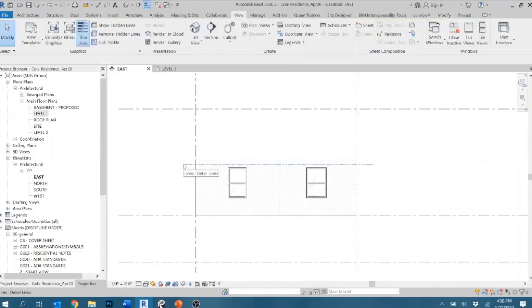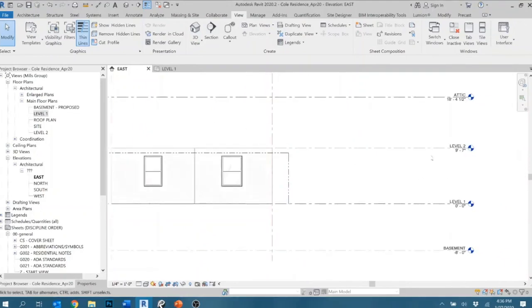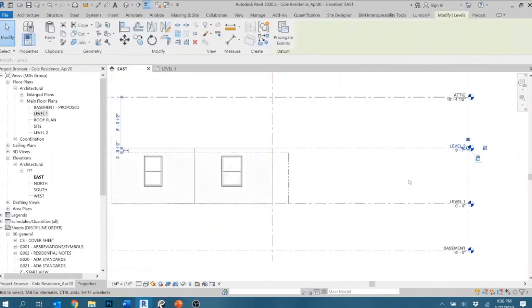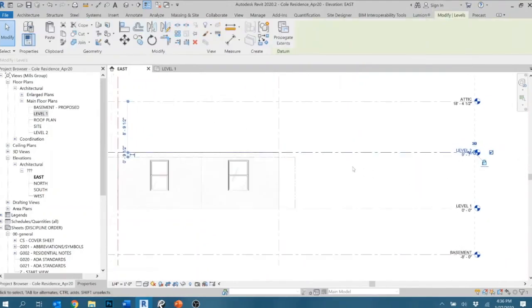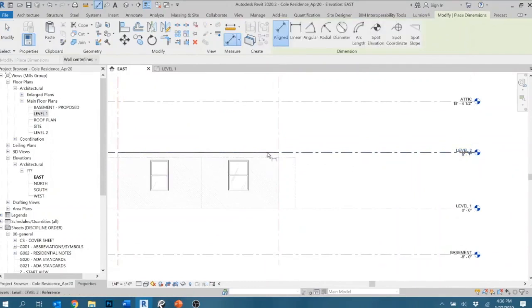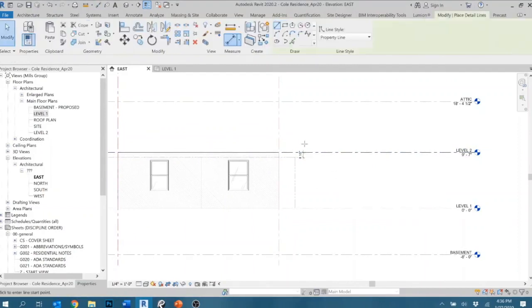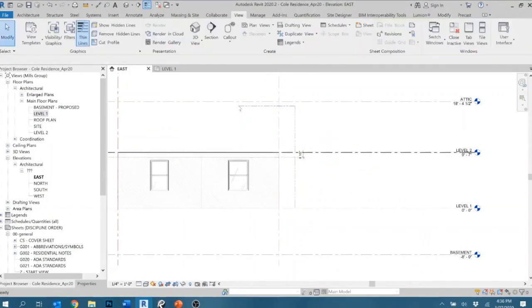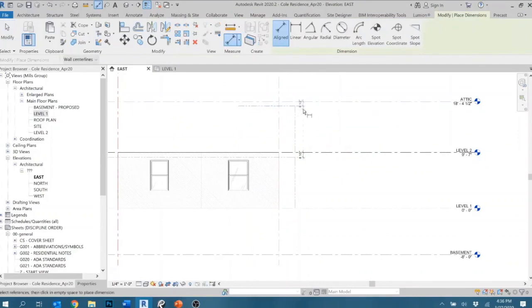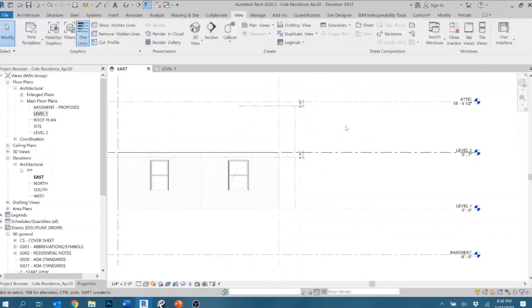The floor-to-floor dimension that I calculated at the stairway was 9'7", so I adjusted my level from level 1 to be 9'7", which means that I have a floor-to-floor of 9.5, which is pretty shallow. Level 2 of the house I am drawing is 8 feet, so in dimensioning that stairway as well, I get the same because it is a usable attic space.